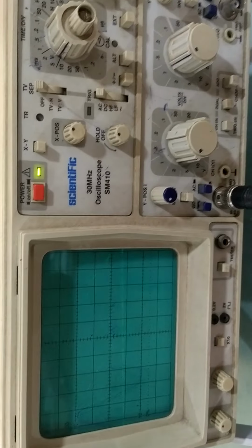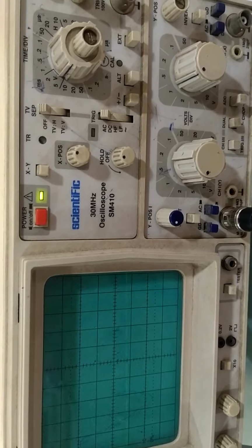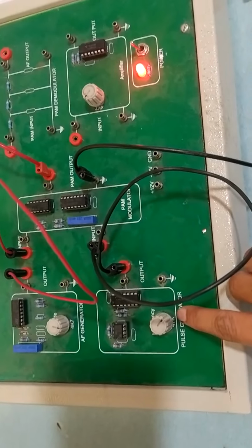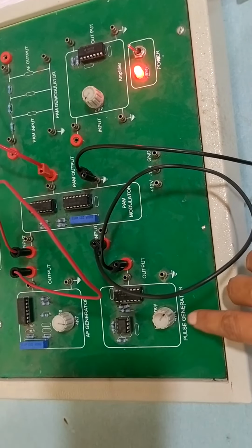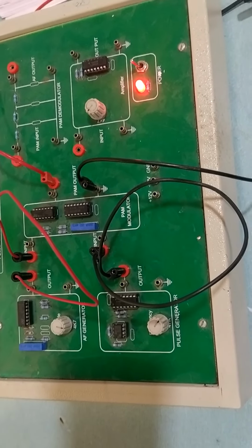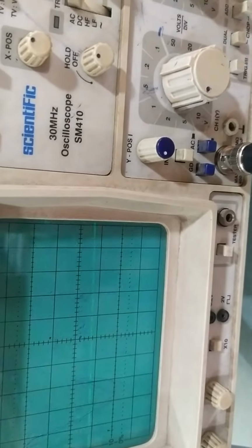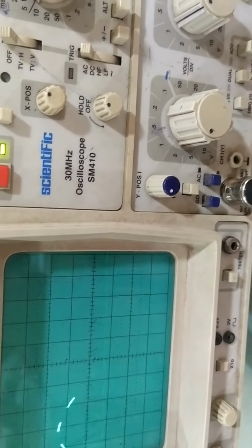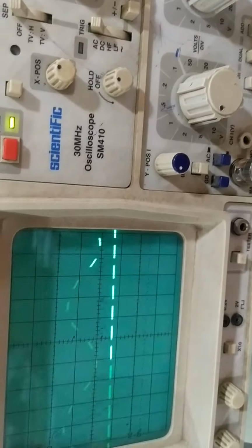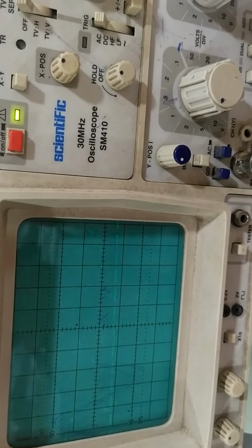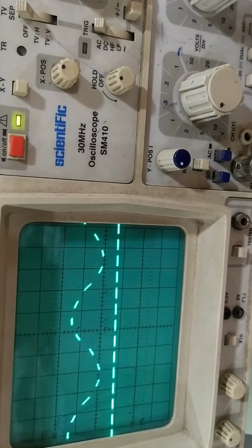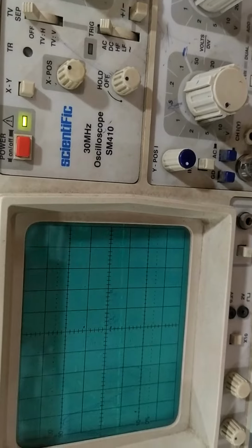Now we will observe the output of a natural sample signal. Our knob of sampling frequency is given here. We have to increase the sampling frequency and observe the effect on the output waveform. For the first step, the sampling frequency is very low, means a part of information is lost here. If we increase or vary the sampling frequency, now as compared to the last, the number of samples increases, so the information loss is reduced.